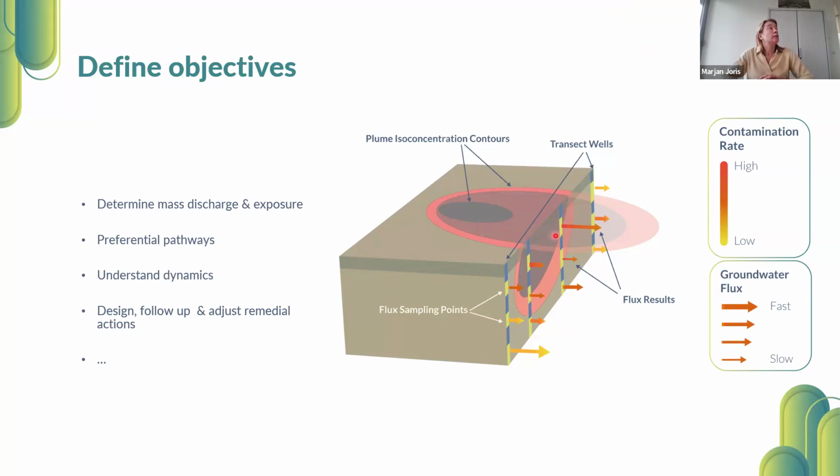Where the cartridges are less suited is for measuring in zones with free phase, like DNAPL or LNAPL, or in fractured bedrock, where contamination is moving by fractures, because we are measuring in wells, and typically drilling will disturb the original state of the geology and influence the flow patterns.